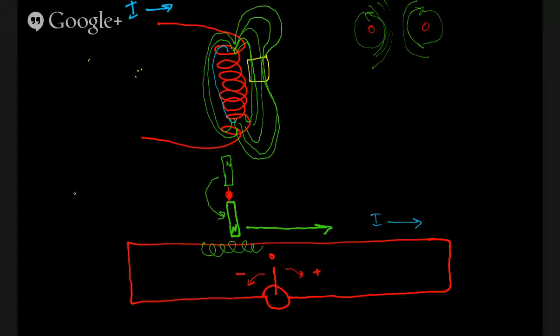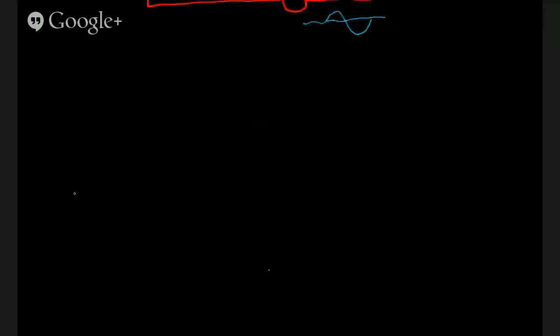So if instead, this would be a DC generator, instead we have an opposite pole here. On this sweep, the North Pole induces a rightward current. Now the South Pole will induce a leftward current. So back and forth, we'd end up with a nice sine wave. And there's our AC generator. Let's look at the waveforms a little closer.